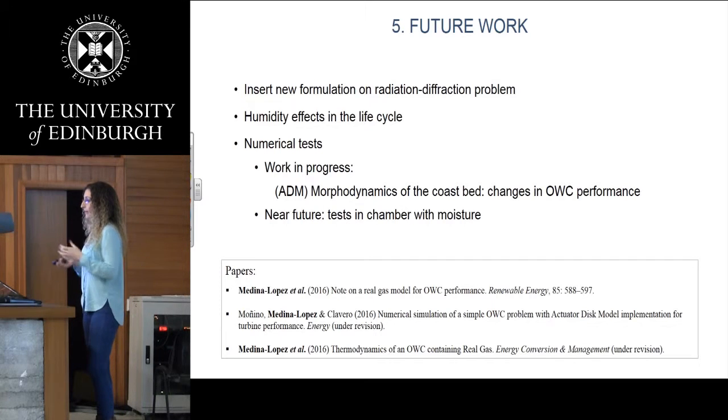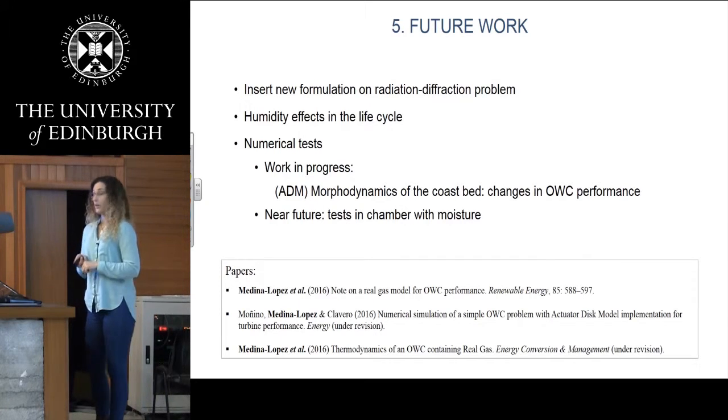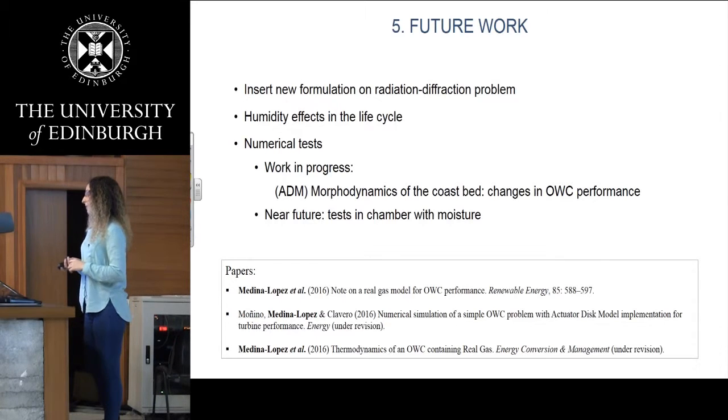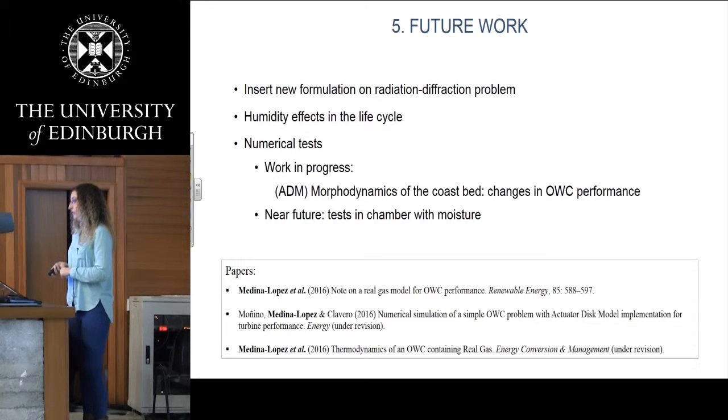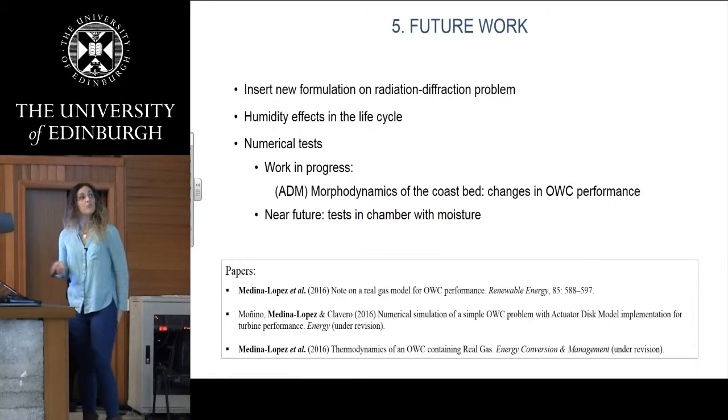I'm doing in parallel some numerical testing in Fluent. So I test an actuator disk model just to simulate the performance of a Wells turbine. I'm applying this actuator disk model to study how the morphodynamics of the coast bed change the OWC performance. And in the future, I'm going to use this actuator disk model to test the same chamber with different degrees of humidity. There are some papers going on.